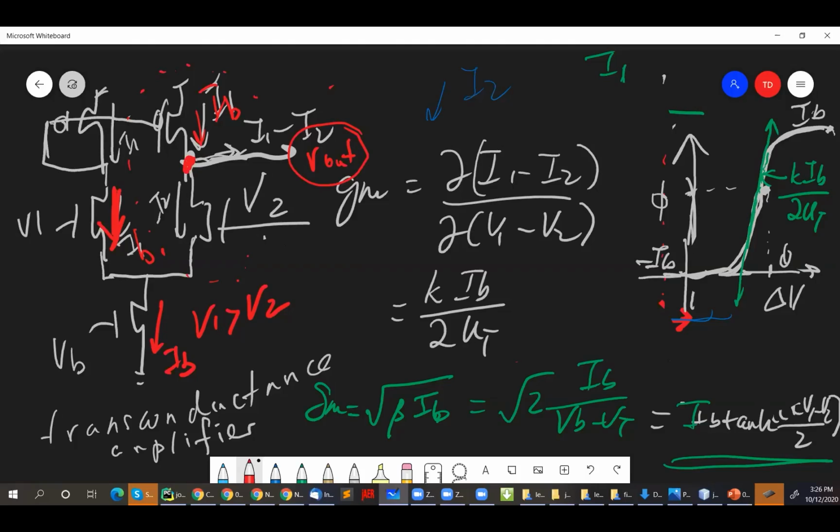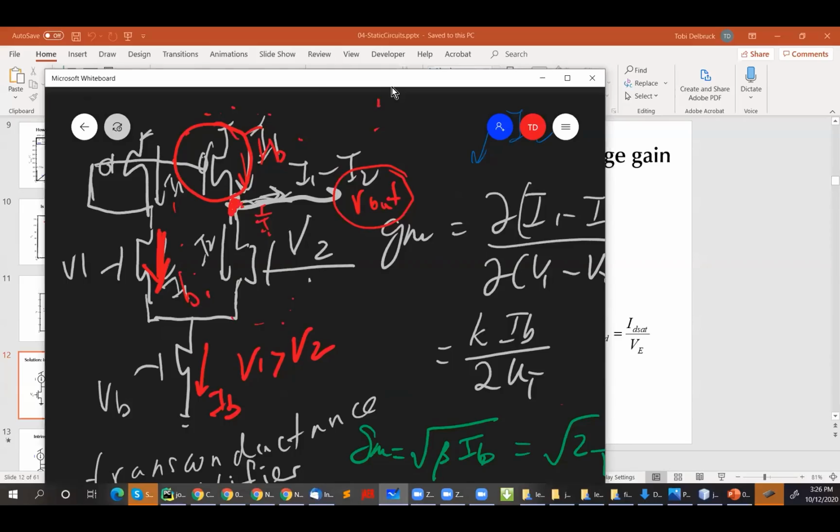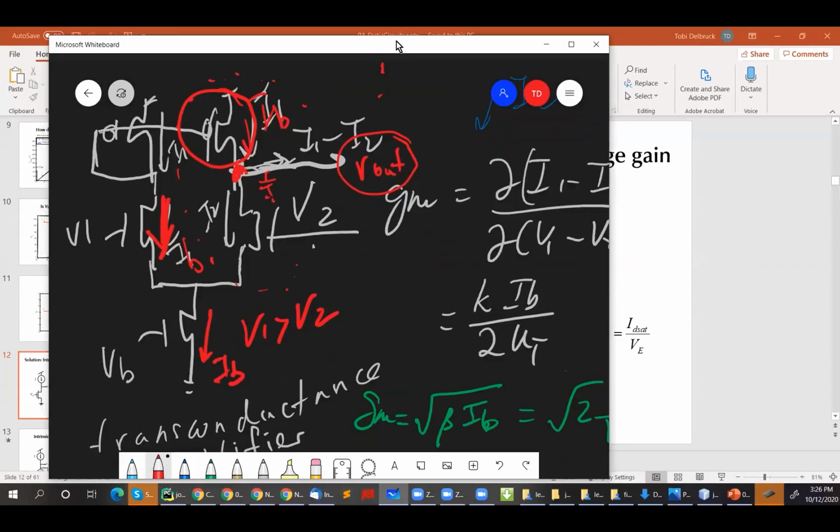So this current is going to charge up this node here. Because again, imagine there's a little capacitor, and I'm going to dump charge on the capacitor. And so that means this voltage is going to go up, up, up, up. At some point, as this voltage goes up, remember this transistor operates in the saturation region only if it's, just remember the I versus VDS curve.